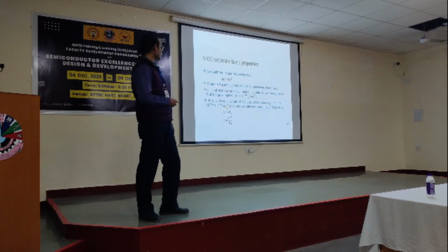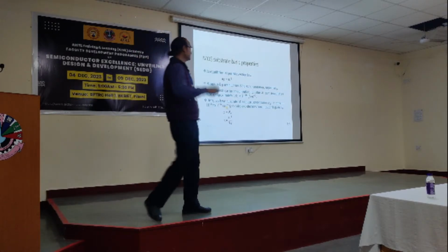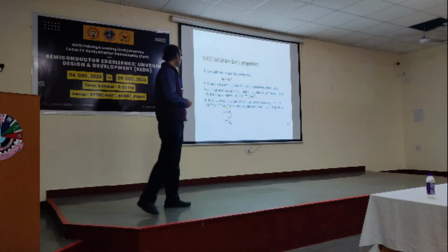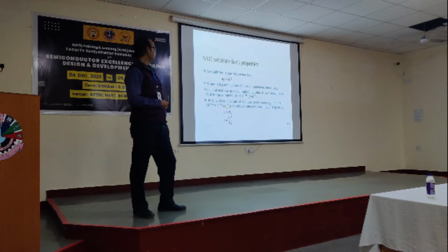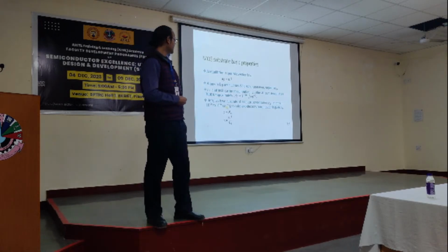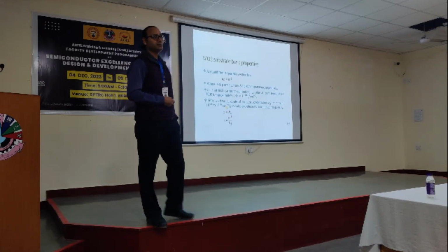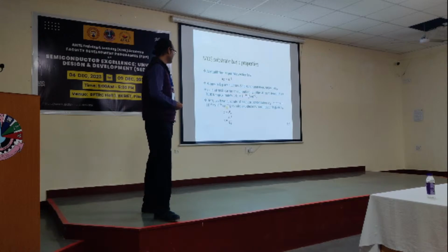Then n, p, electron and hole concentration, right? Ni is the intrinsic concentration. Intrinsic means, again, without any doping. I hope you know that concept. For example, in silicon at 300 Kelvin, around 25 to 27 degrees centigrade, it is 1.5 into 10 to the power 10 per centimeter cube. So at this point there is a mistake here. Sorry, this is 1.45 into 10 to the power 10.